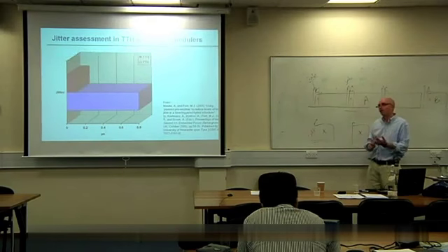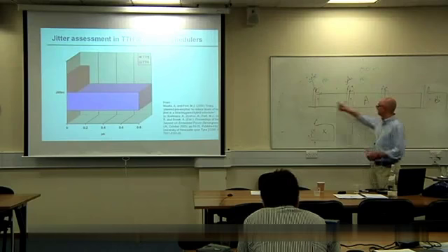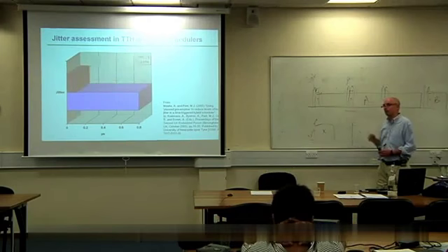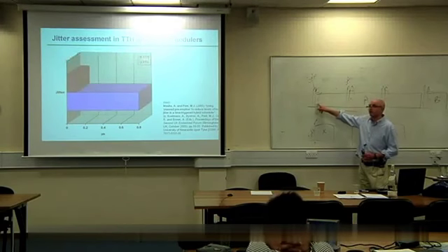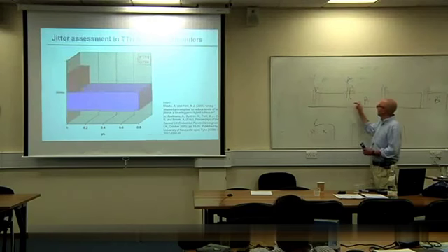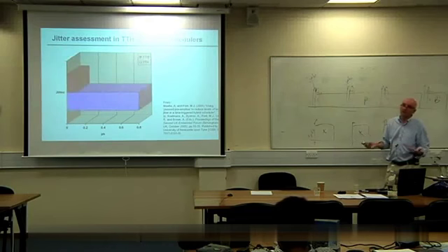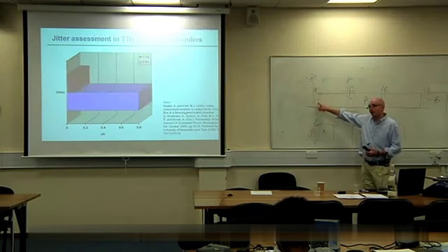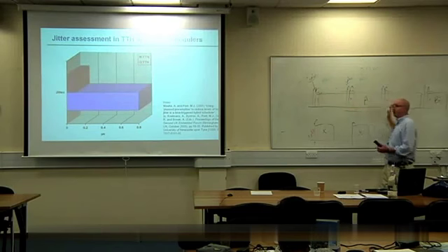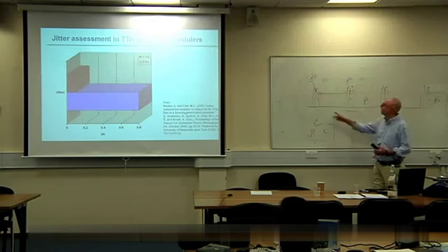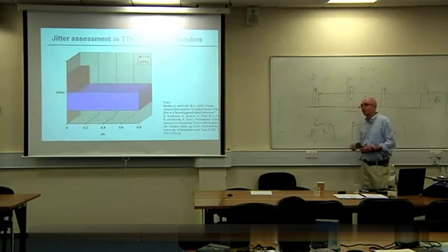Now, if you have a look at the exercise we've set you today, basically this is an exercise, and we've added the tweak in, which is representative of the real world. Suppose I give you a scenario where I say I want to control an ADC doing an FFT type task, which is not uncommon in digital signal processing type applications. ADC and fast Fourier transform. What we've said in the exercise is I want to vary it. It might be a 256, it might be a 128 sample FFT, fair enough. But we've also said, oh, but I want to change the sample interval live.